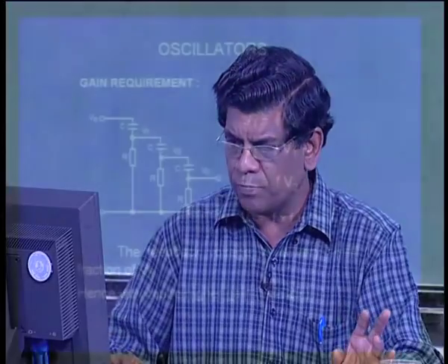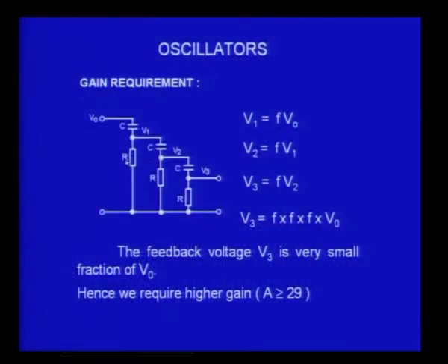Ideally it is like that, but in the actual case it is not, because if I take this R, the potential divider is between the C and this R, that is what you assume. That will be true only if you do not take into account the effect of the presence of the other RC networks, because they are all connected in parallel.